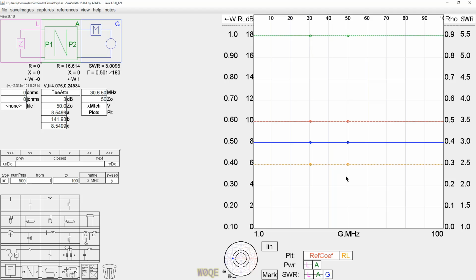So this is interesting. Notice how we have a return loss here of 6 dB. We have an attenuator of 3 dB. Our 3 dB attenuator took the power that came into the circuit, which was 1 watt, halved it, 100% of that was reflected, halved it again, and what do we get back? 1/4 the power, 6 dB. So a lot of components like attenuators, and for that matter even industrial antennas, are specified in return loss. You'll see an antenna that has a return loss characteristic versus frequency. That can be converted to an SWR plot, although not generally in your head.